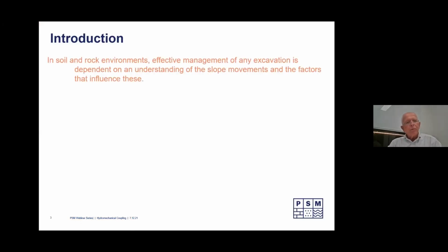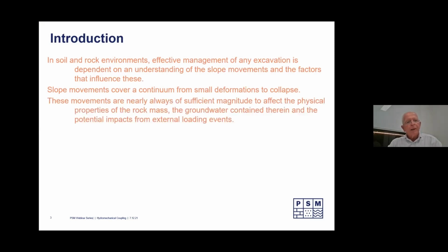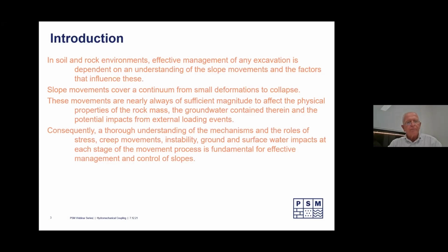So in soil and rock environments, I believe you can't effectively manage any excavation unless you understand the slope movements and what affects those. And there's a continuum of movements, obviously, from very small elastic deformations right through to collapse. And those movements are nearly always of sufficient magnitude to change the physical properties. And therefore, they also change the groundwater. And there's an impact also from external loading events.